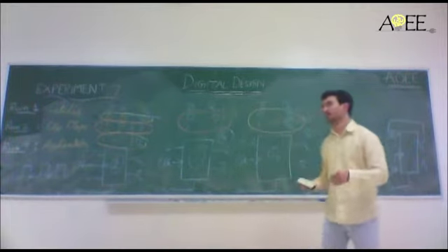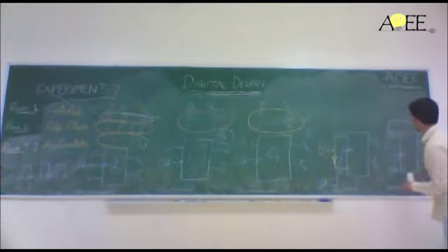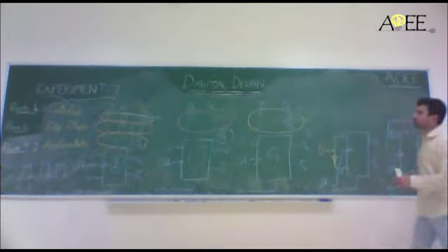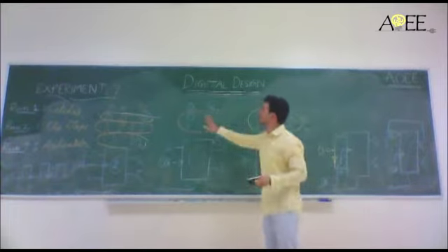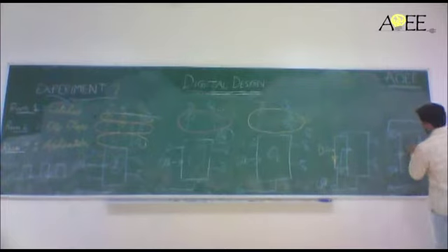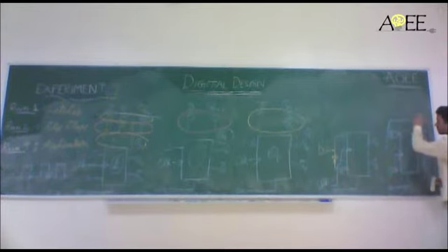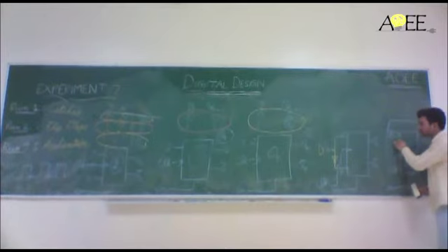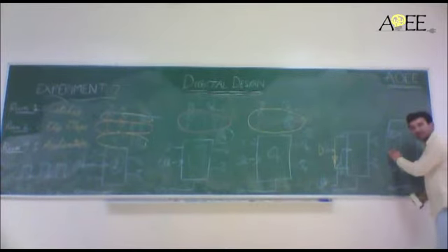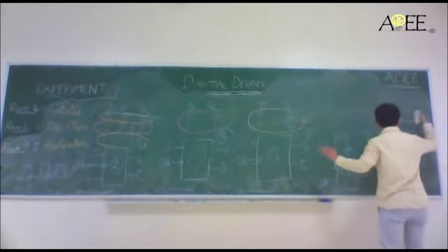Now I have to make a T flip-flop out of a D flip-flop, which is over here. Yes, this is a D flip-flop. So the idea behind using D and T is a kind of toggle. Taking the Q output, that is the output that was there after the pulse was applied, this output is fed into the flip-flop directly using an XOR gate. What will the XOR gate do? If T is equal to 0, I will get Q directly.